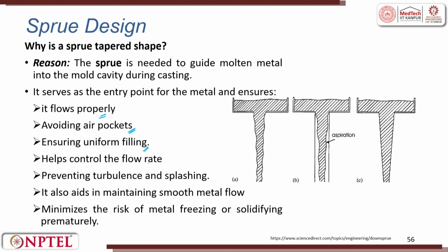It helps the flow control. It prevents turbulence and splashing. It also aids in maintaining smooth metal flow. It minimizes the risk of metal freezing or solidifying prematurely. So, for all these things, you need to have a taper.